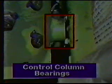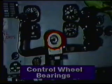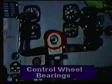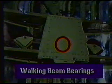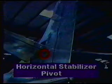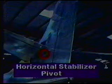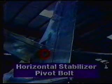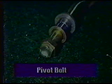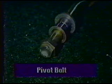Flap hinges are contained in assemblies referred to as flap bearing links. The two units on either side of the control column are called the control column bearings. The two units that support the control wheel are called the control wheel bearings. The units that the walking beam pivots on are called walking beam bearings. The major pivot for the horizontal stabilizers is called the horizontal stabilizer pivot, sometimes called the horizontal stabilizer pivot bolt. The actual bolt itself is really two entirely separate units that create an assembly, usually called the pivot bolt.